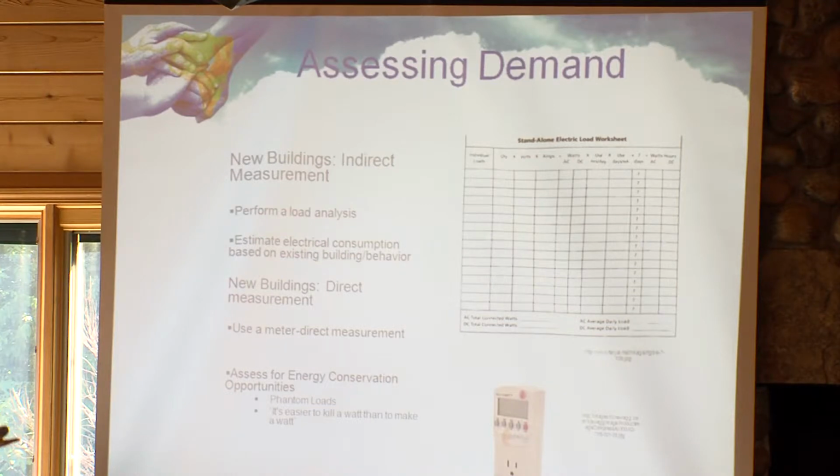This is an example of how you assess or size up your demand. And if you're kind of geeky like me, you want to go around and figure out what your load is. Essentially create a load profile. Well, we have all these lights here. There's 1, 2, 3, 4, 5, and what's the wattage on it? That's essentially what is involved when you're doing a load profile.